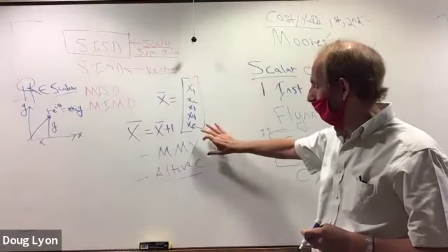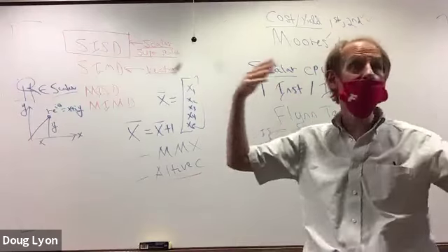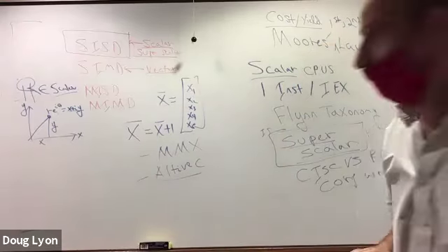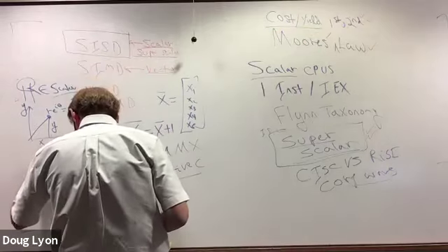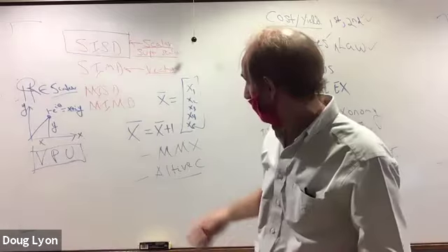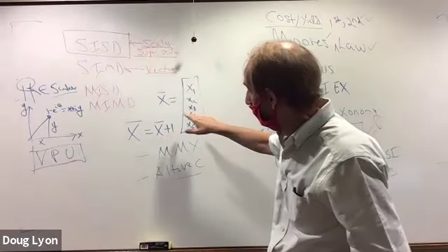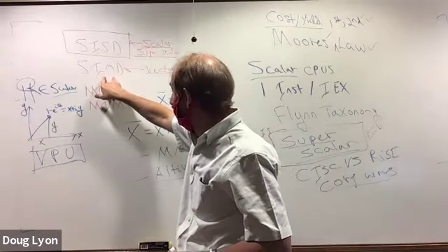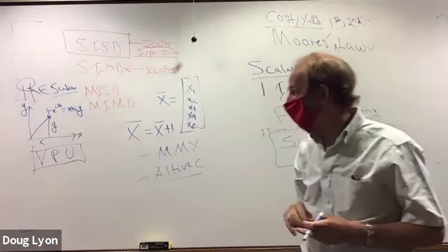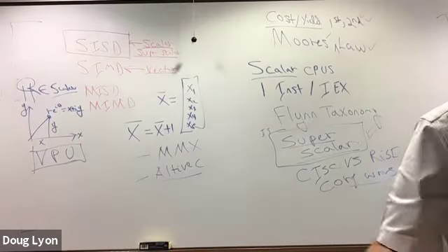And so what they did was they incorporated these instructions directly into the CPU. You say you're going to double the number of transistors. What are we going to do with all those transistors? This is the kind of thing we do. We put in a vector processing unit, or VPU. You put the vector processing unit into the CPU, and now you have the ability to take several pieces of data and operate on them all at the same time, turning your CPU into a SIMD-compliant architecture.